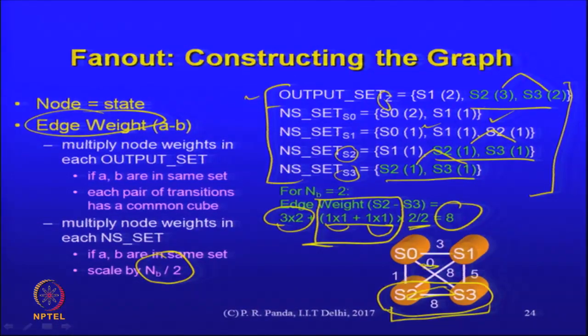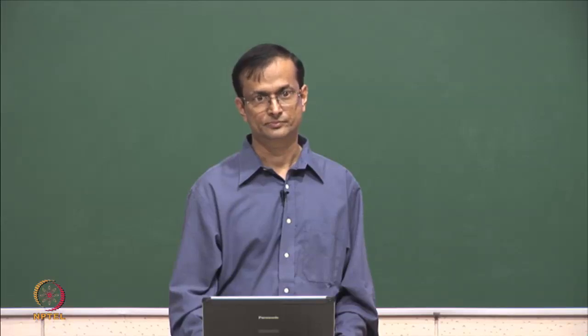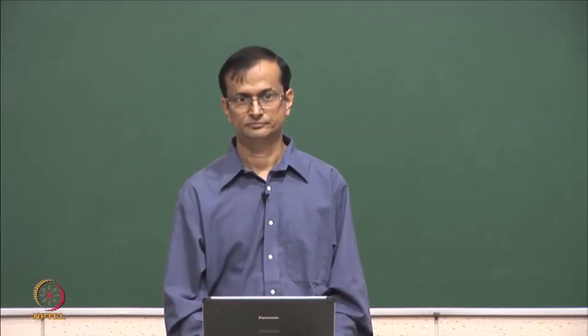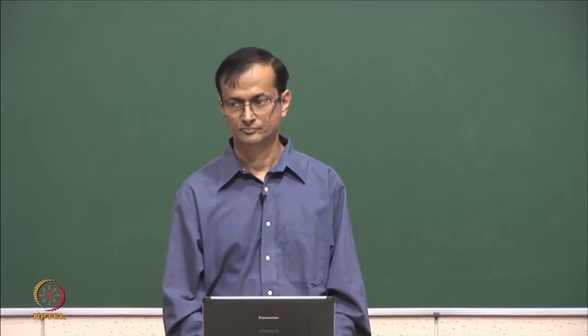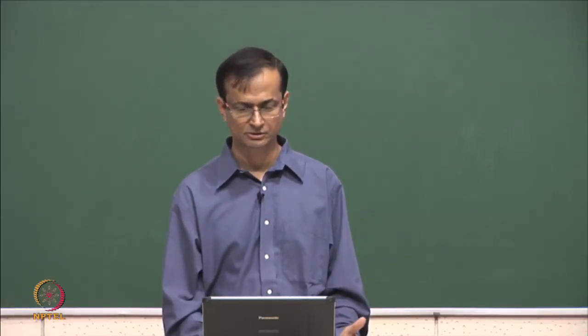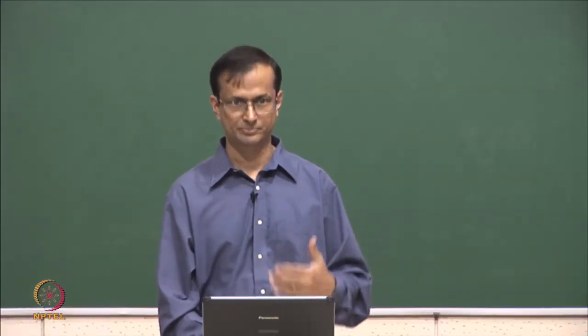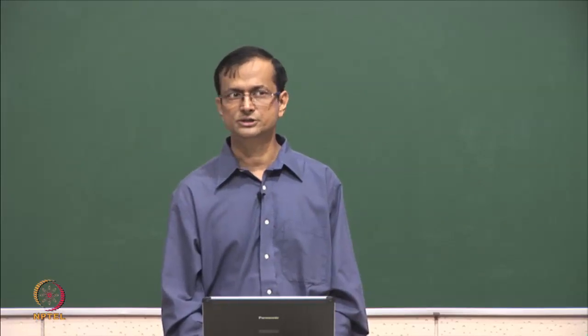So one more question. Yeah. Here the outputs were fixed 0 and 1. Somewhere a decision has happened that my output has to be 0 or 1. But typically when we are designing the architecture, we have flexibility of deciding the output states also when two FSMs are going to interact. Like when I am partitioning the bigger design into smaller designs, I have flexibility of changing the output bit definitions also. It's up to me. Yeah, in fact, even here in our context of HLS, where did the FSM come from? This is the output of the HLS step, right? Do we have a choice with respect to these outputs?